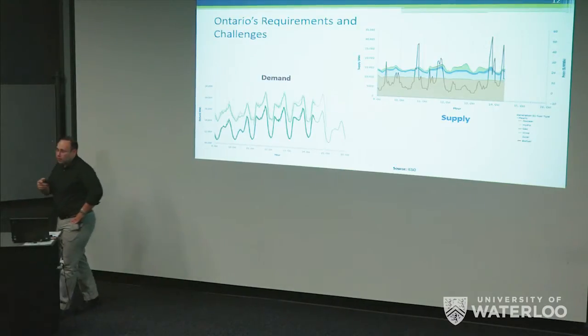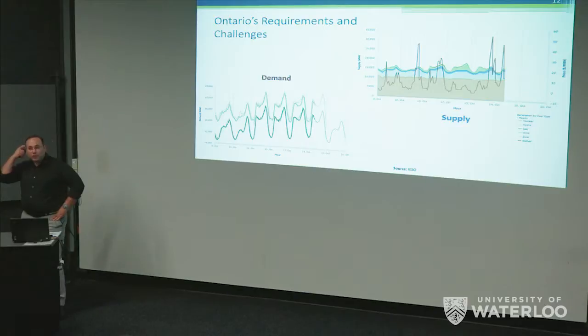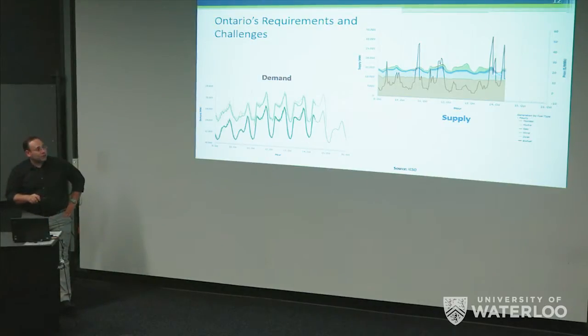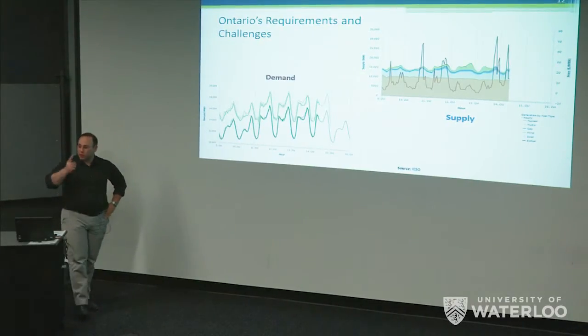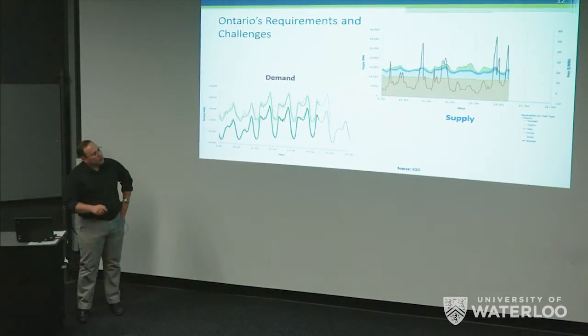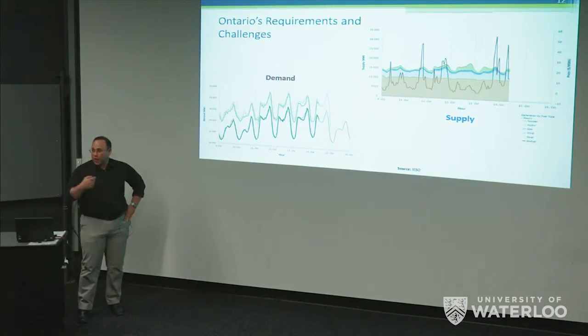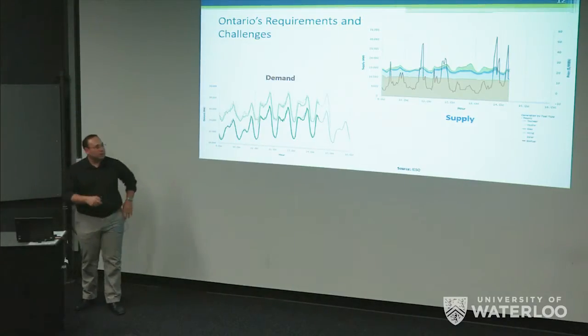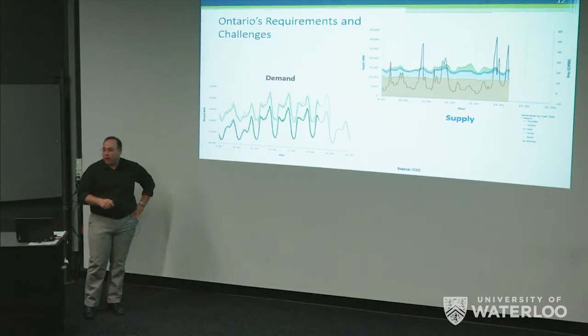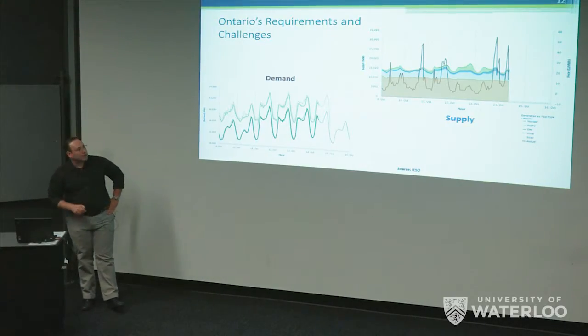So within Ontario, when you have more wind generation, the average price of electricity will drop. What will happen, though, is that the price of ancillary service will shoot up. So this is the price that you generate in the market. The average gas turbine cannot compete, so the peaking power starts working to make up for that, which will increase the price 3-fold or 4-fold at the same time.